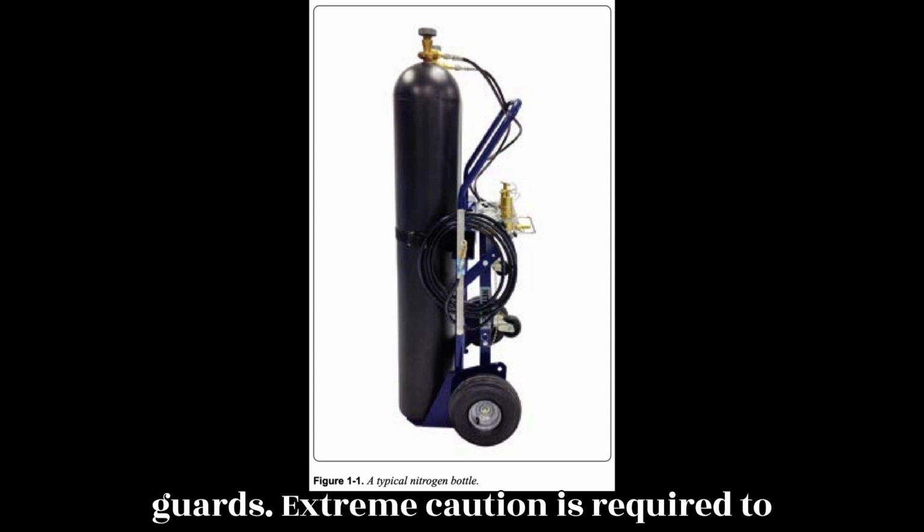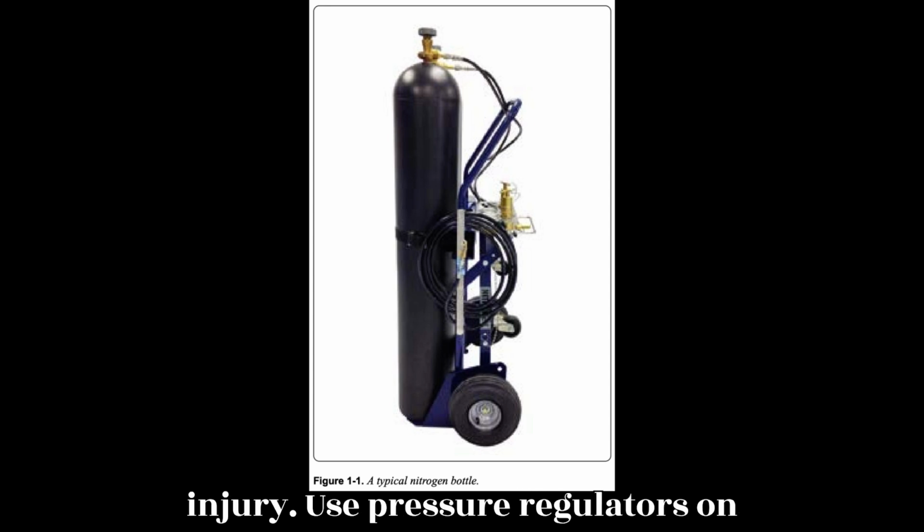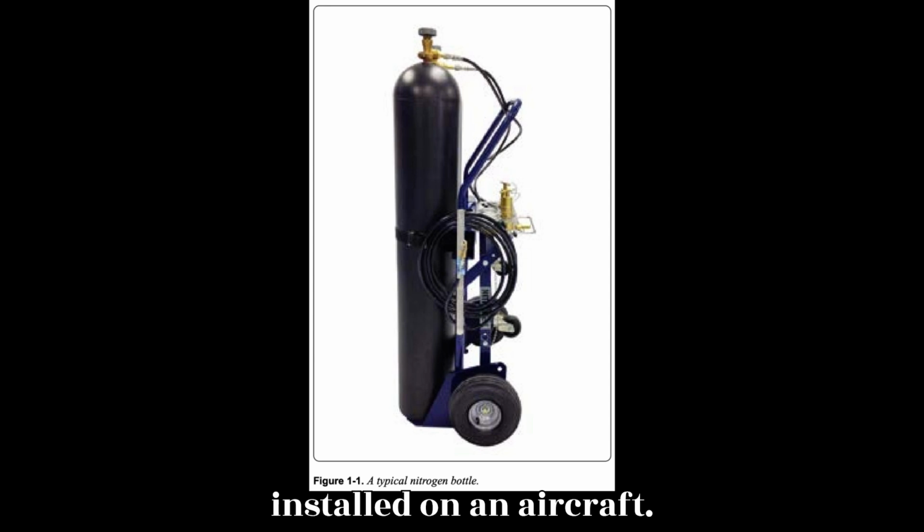Extreme caution is required to avoid overinflation of high-pressure tires because of possible personal injury. Use pressure regulators on high-pressure air bottles to eliminate the possibility of overinflation of tires. Tire cages are not required when adjusting pressure in tires installed on an aircraft.